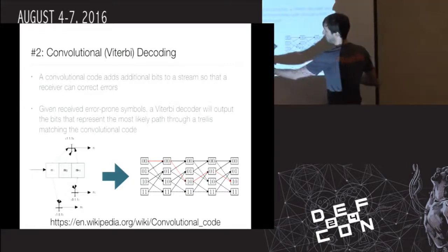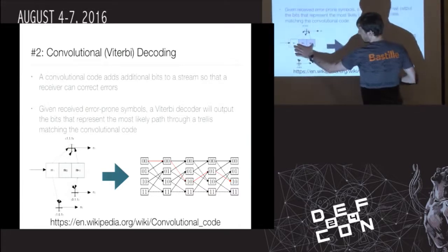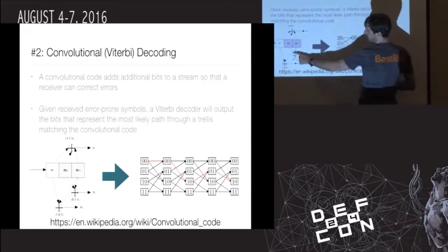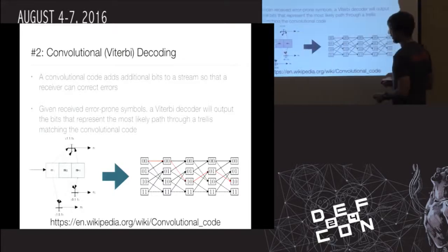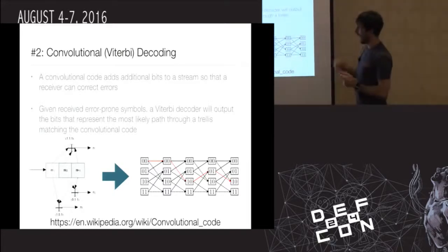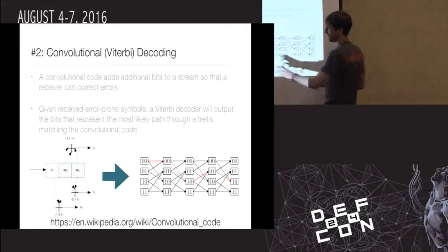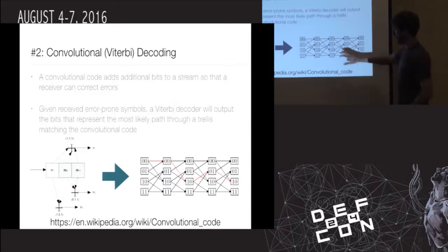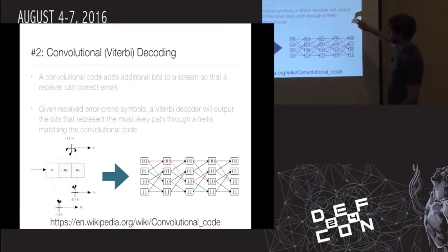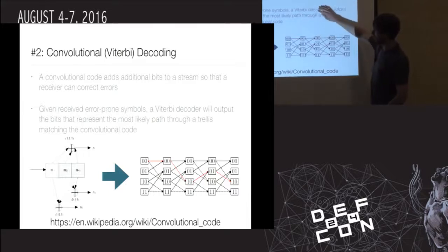But what you do is you feed your data bits into a buffer, and then you basically take these taps off and produce extra bits for the incoming bits. And then that adds the redundancy. So depending on the polynomial that you've used, how you've configured this, then you can generate this trellis, it's called. I won't go into details because it's a bit outside the scope here, but you can use a decoder then.